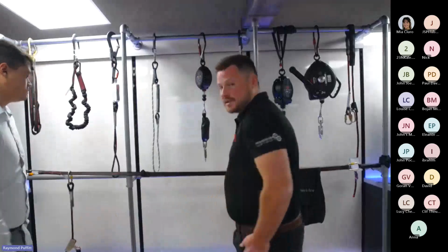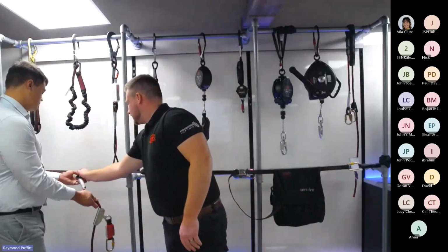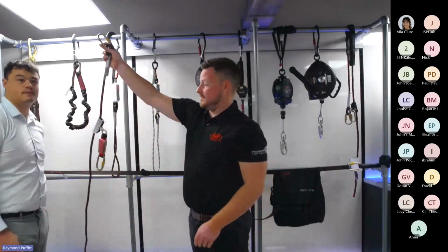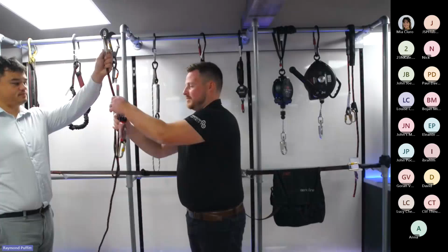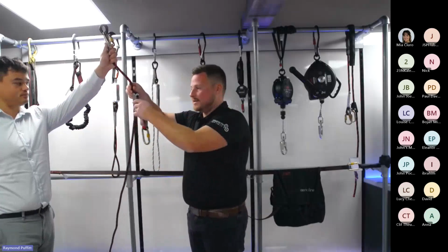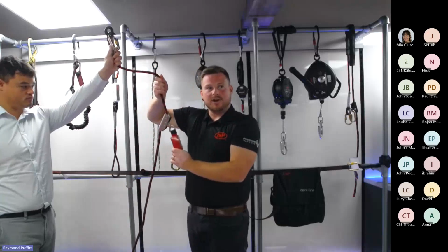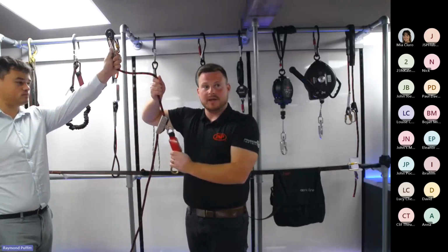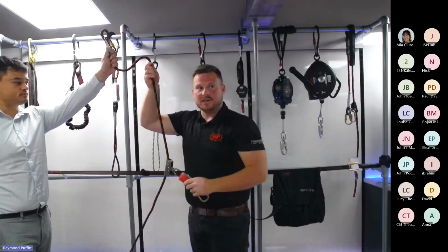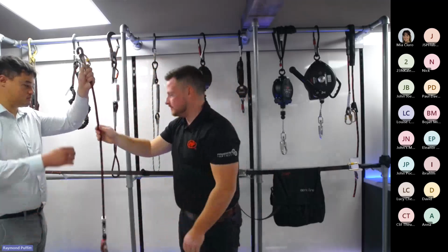Another type of fall arrest is we have a rope and grab system. So if you can just grab that one from Harry here, just take that off there. So you hold it up so we can see it. That's it. Just hold it up like that for me. So the way these work, the user will move it up and down the rope. So you can see that there. If I was to slip or fall, that will come onto the rope and it will catch them a lot quicker. Okay. You see people going up and down ladders with these attached all the time. Just a nice way to reduce the fall distance of that. Okay. Catches them nice and quick.